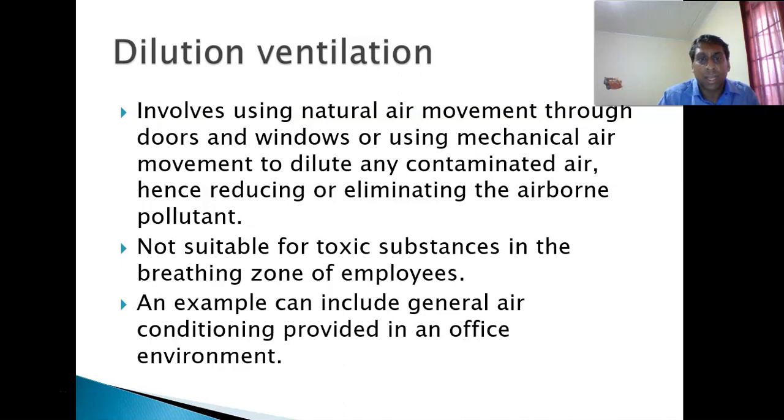Dilute ventilation involves using natural air movement through doors and windows, or using mechanical air movement, to dilute any contaminated air, hence reducing or eliminating the airborne pollutant. It is not suitable for toxic substances in the breathing zone of the employee. An example can include general air conditioning provided in an office environment.